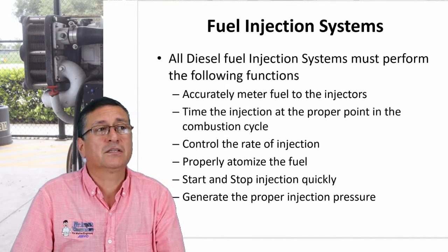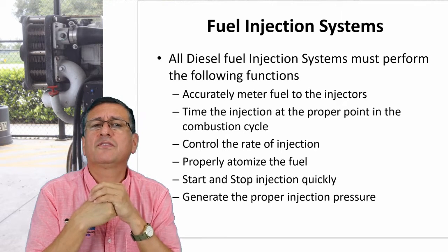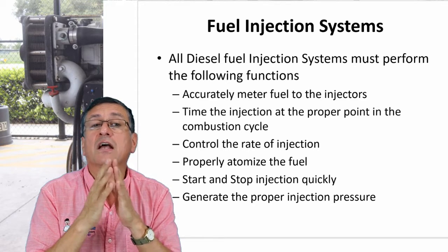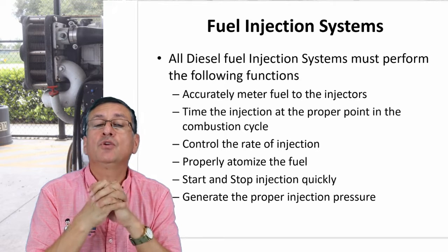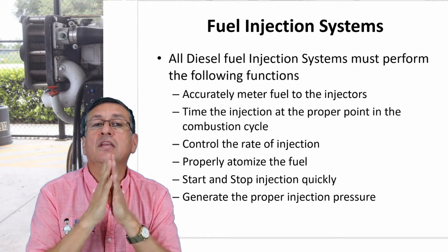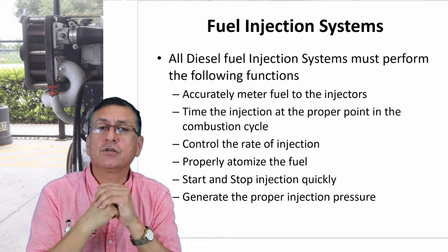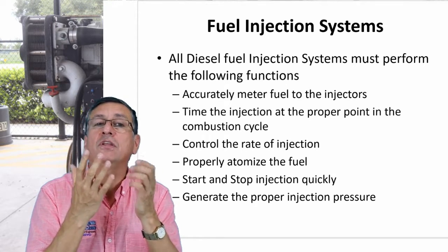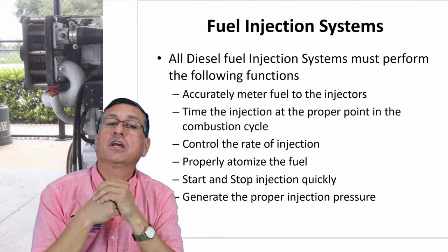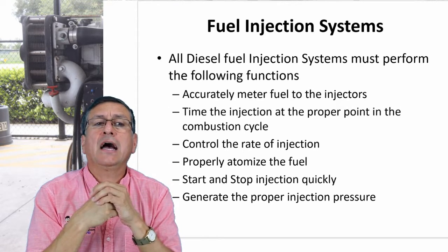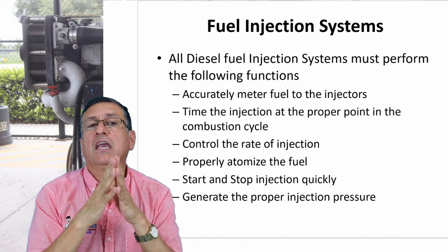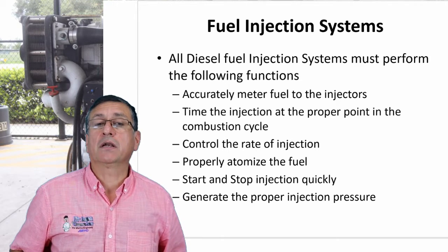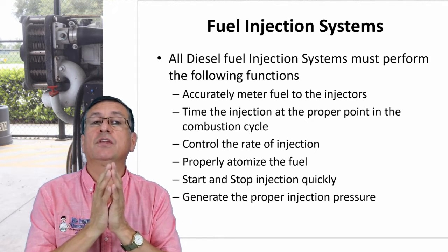The injectors are critical. How often should the injectors be serviced? Once again, it depends on the manufacturer's recommendations, but normally it is around every 1,000 hours. You need to remove the injectors and send them to the machine shop in order to calibrate them. Or if you have the tool, I am going to show you the tool today in this video. If you have the tool, you can check if the injector opens at the proper pressure, and additionally you can check if the pattern of the fuel going out is the appropriate pattern. But you need experience and the tool to do that.